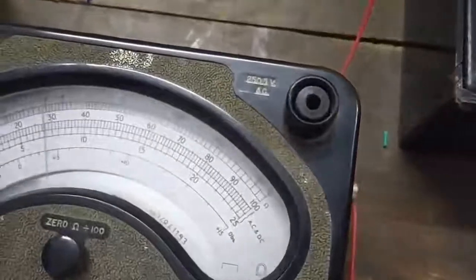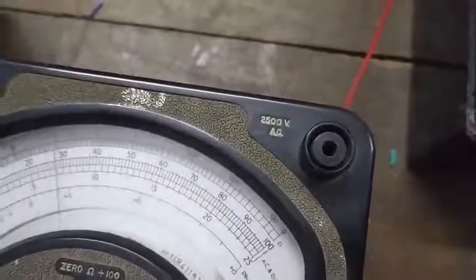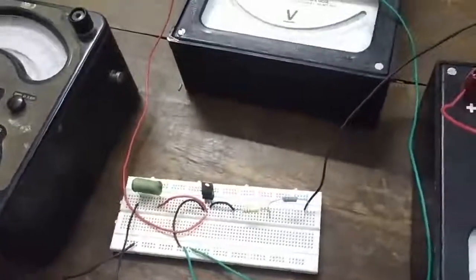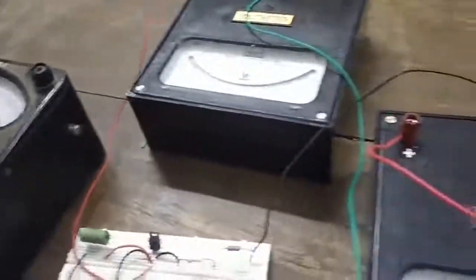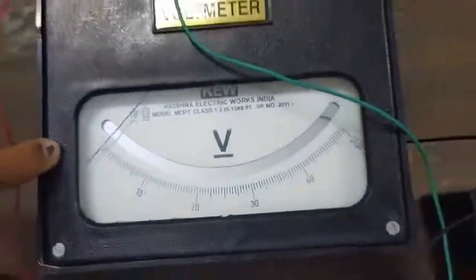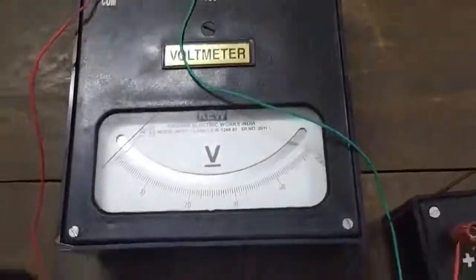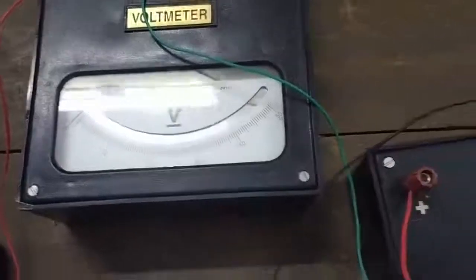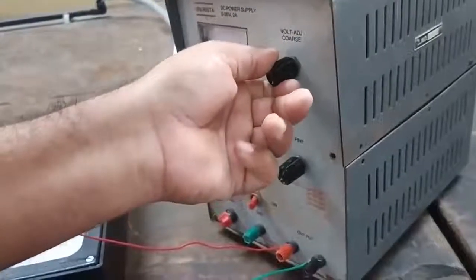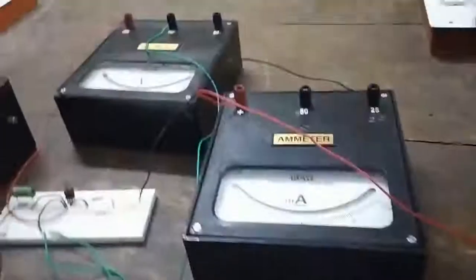Now I change the reading range. Now it is showing 290 milliamps. Okay. Now this is the current through the SCR after turning on. Now this is the voltage. It is around 1 volt. It is now turned on. Now to find out the holding current, you just reduce the gate current to 0, then reduce the voltage.